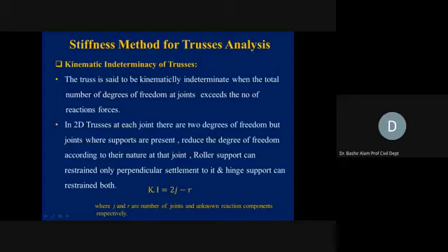So, restraint of the displacement is coming from where? It is coming from the capability of the reaction. If we take the example of the hinge support, it can resist in the vertical direction, and it can resist in the horizontal direction also. So horizontal and vertical displacements are going to be equal to 0.